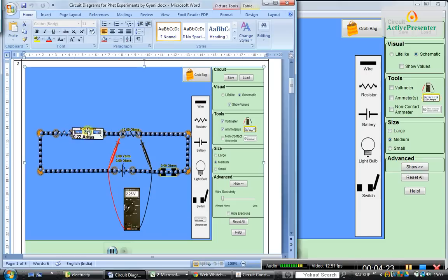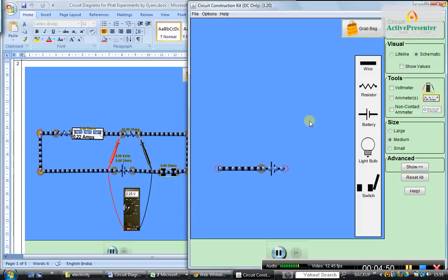So I can see what new current I am producing using this ammeter, and for that new current I can measure the new voltage which is dropped across this using this voltmeter. We know that by Ohm's law, potential difference across this resistance V will be I into R, where R is this fixed resistance and I is the changing current. I hope now it is clear. Yes, sir. Okay.